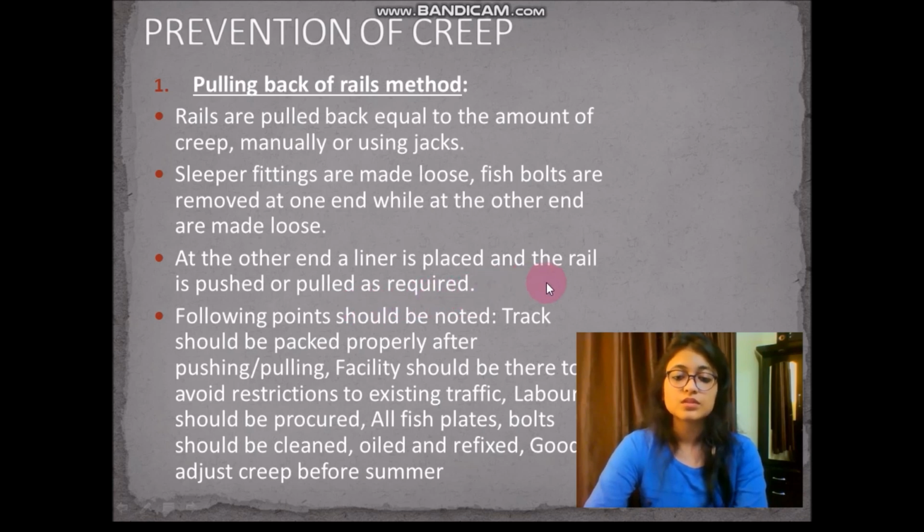Following points should be noted. Track should be packed properly after pushing or pulling. Whenever we have eliminated the creep, after removing the creep, the track should be packed properly.